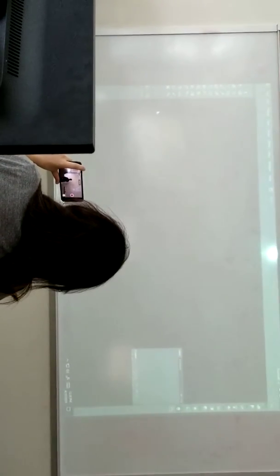Command lines. What does command line mean? You could type the command. I can just start typing, and I can literally do anything based off of typing in the command. And then the cool thing about AutoCAD, I can start typing. I type C. All the commands that start with C come up, and it filters out as I continue typing. So I can literally guess a command, type it to see if AutoCAD has it.